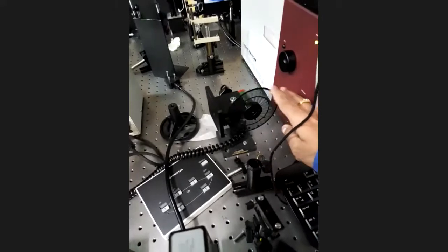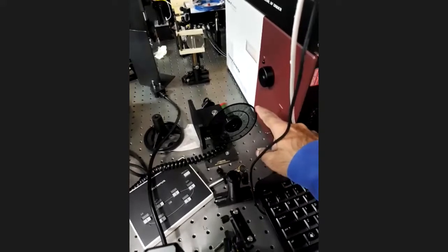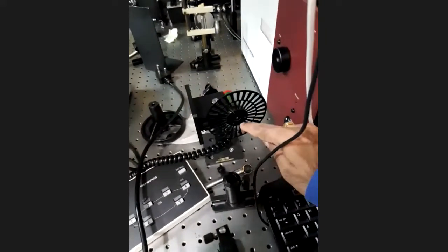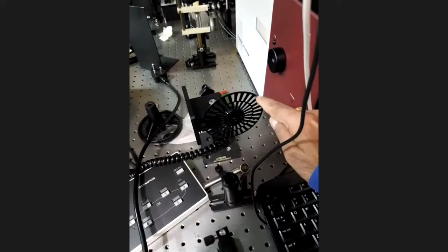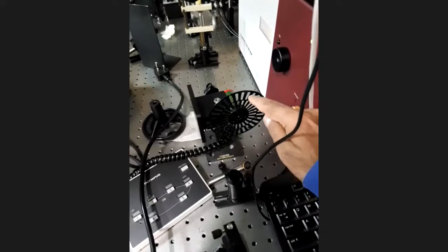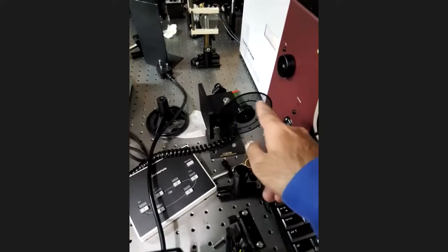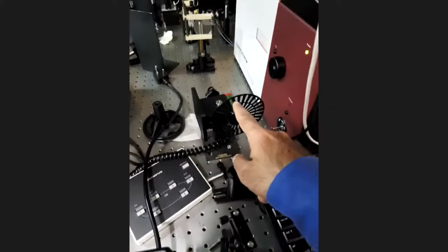So we also use another tool to improve the signal to noise. So we use something like this. This is a chopper. This is a mechanical chopper, a wheel which can be turned at very high speeds. If you see here, there are inner and outer slots. They are not the same, so inner and outer slots are different. So you can put a beam coming through this, and you can modulate it, so you're making it on, off like that. So you're making pulses at some reference frequency at which you're chopping your light beam.